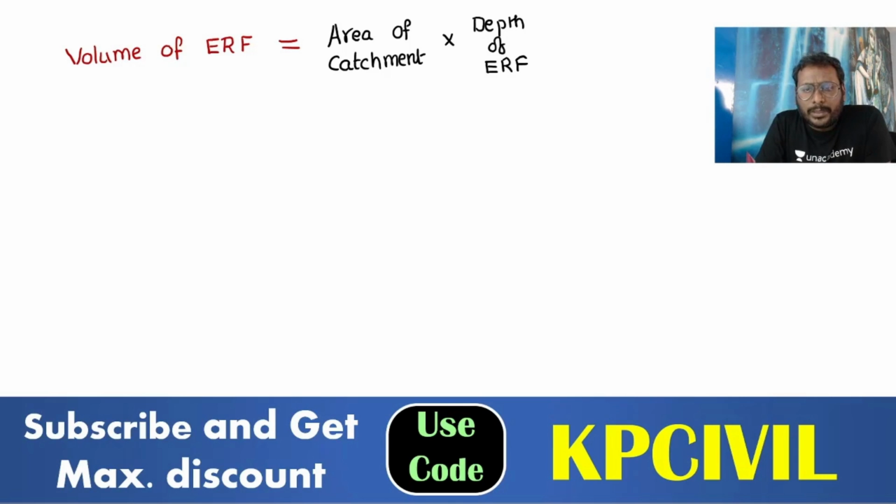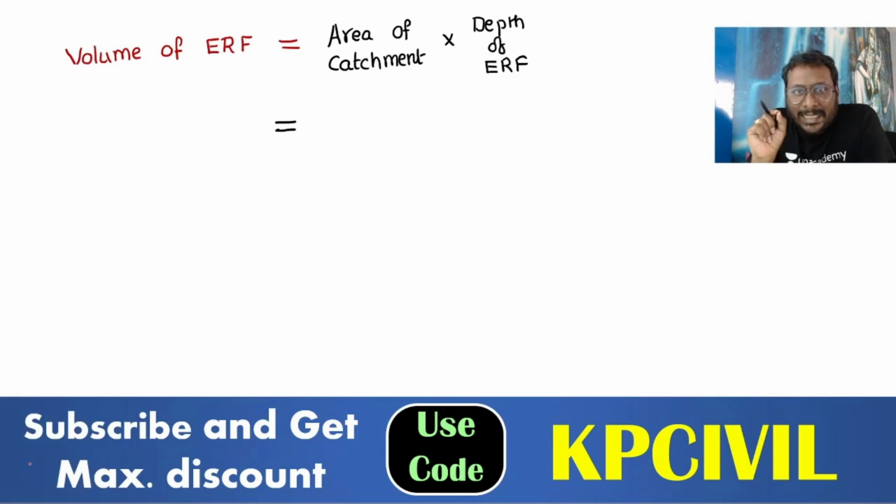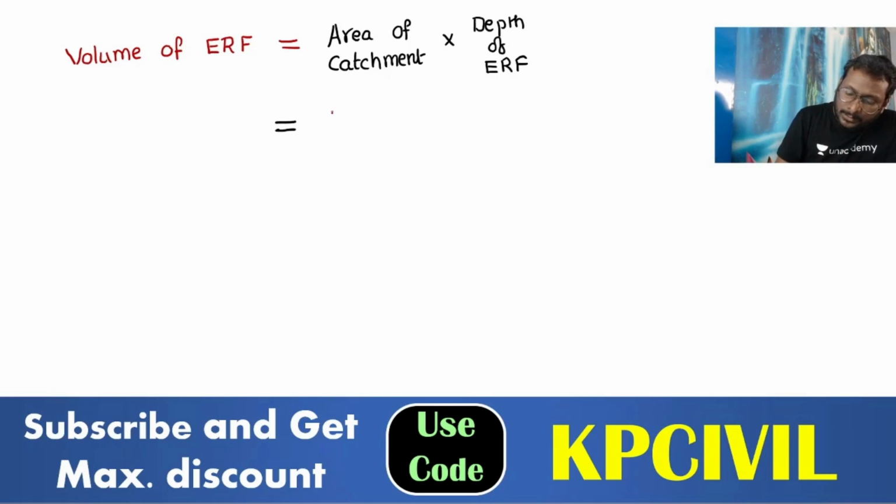Volume of effective rainfall is equal to area of catchment into depth of effective rainfall. The same thing we will express with another formula, because it is a triangular direct runoff hydrograph. So it is the area of a triangle, half into base into height.